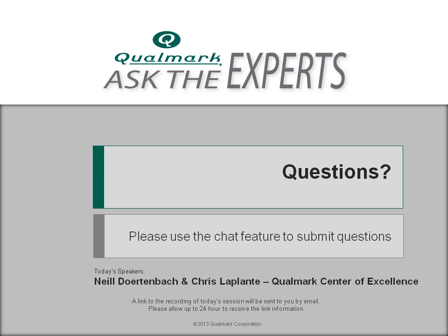Okay, thank you. Another question is, what is the difference if the profile starts at cold temperature rather than starting at hot? What are the ramifications? Really, the only one doesn't have too much to do with HALT or with HASS directly, but the fact that when you close the chamber doors, the chamber is full of room air with its associated humidity. If you start with a cold cycle, you have a reasonable chance of condensing that humidity out on the walls and on your product and getting frost.